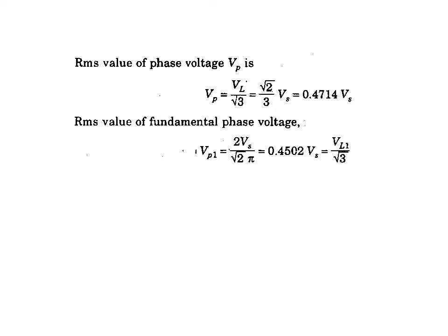That means thyristor T1 will conduct for 180 degrees, and in the next cycle thyristor T4 will conduct for 180 degrees. So the upper group of thyristors, that is T1, T3, T5, conducts at intervals of 120 degrees, and similarly it is applicable for the lower group of thyristors. So this is about the 180 degree mode of operation of three phase inverters.